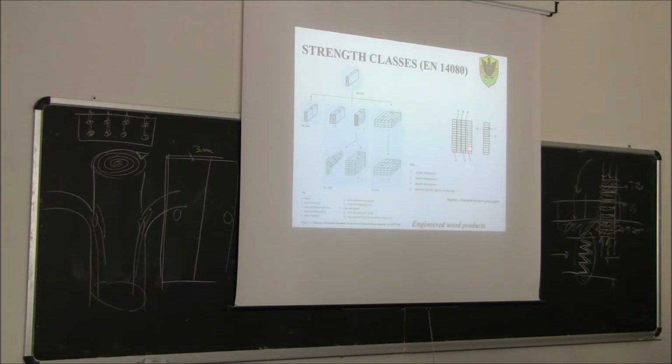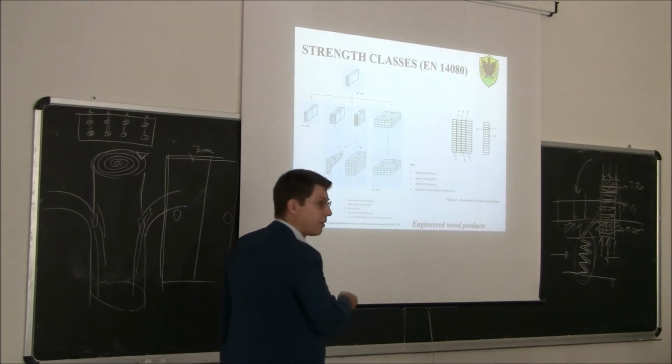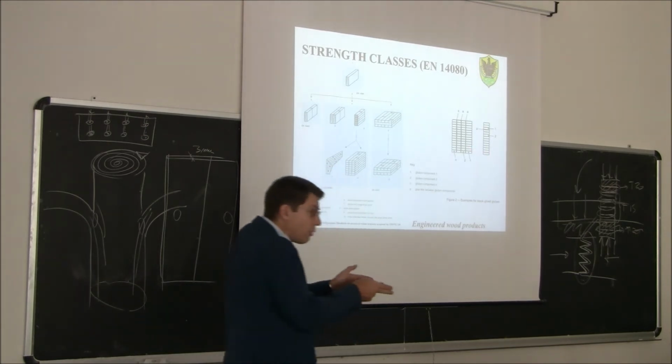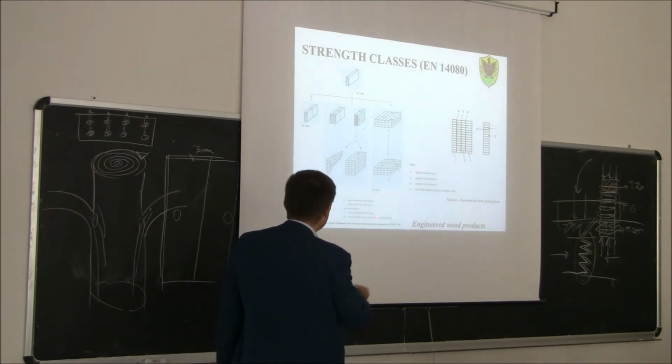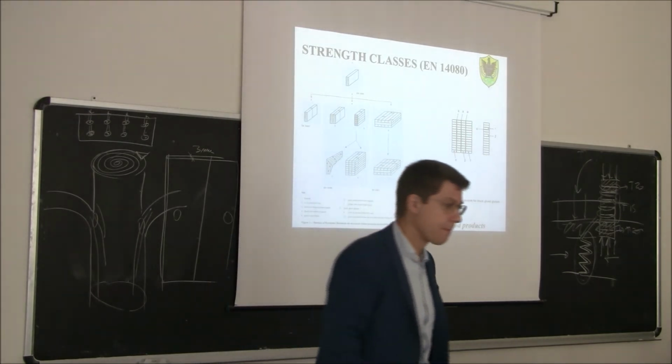So, for example, in this case you see we have a very big cross-section, 4 glue-lam members that have been glued along these vertical surfaces. So we have, if you want, 3 different gluing processes. First, you have the gluing of the finger joints between the lamination. Then you have the glue of the lamination between lamination, and then you have the glue between different glue-lam members on the side in order to get what is called block glue-lam. Okay?